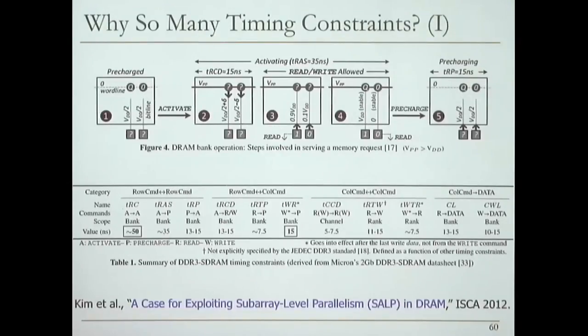The reason we have this is simple. It's synchronous. You don't need to design that asynchronous circuitry and the handshake related to it, and you can also get, hopefully, the best latency. But we'll talk about latency even more later. This is true for many other controllers also. If you look at a flash controller, you have similar timing constraints there as well, and even weirder ones that we're not going to talk about at the moment, at least.